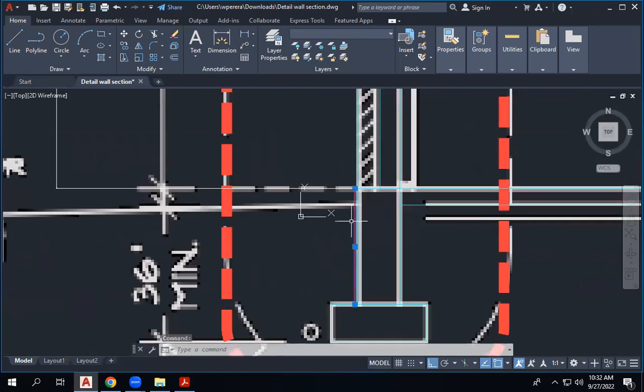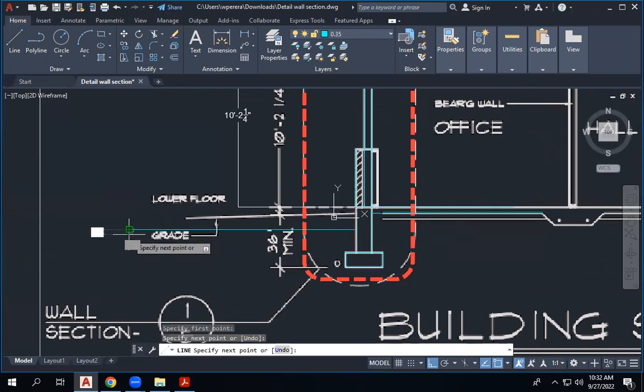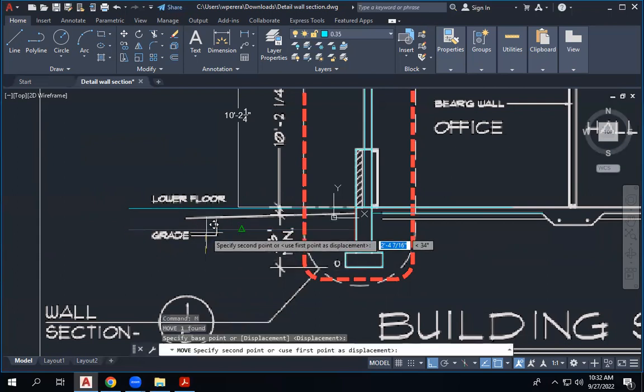This vapor barrier, see now, this shows the lower floor level. That is the level of the slab inside the building, but outside it will be soil. The soil should definitely be lower than the floor level. If you have it on top, it can't be here, it could be the same level or lower. Do you understand that?